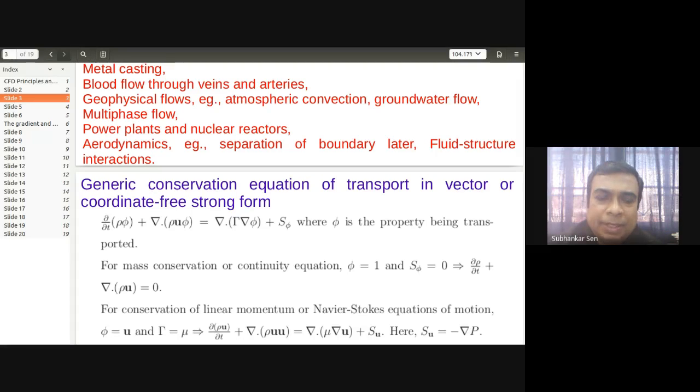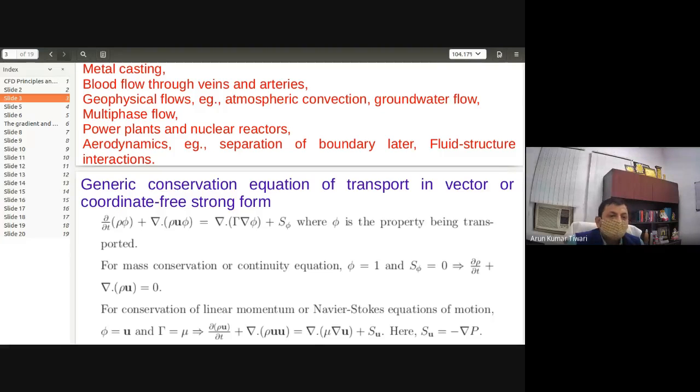So this left hand side represents the acceleration term. If the acceleration term, or the nonlinear terms, are zero, only in that case the flow becomes a linear second order partial differential equation, and then we may be able to solve these problems.